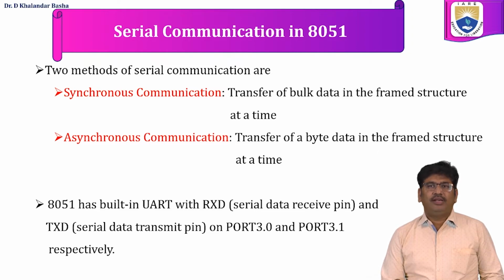8051 has a built-in UART with the RxD line, which is the serial data receive pin, and TxD, the serial data transmit pin, on port 3.0 and port 3.1 respectively.